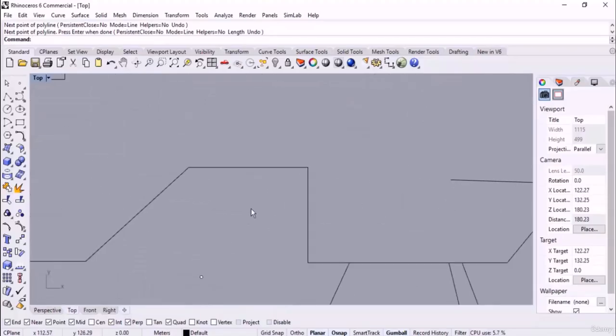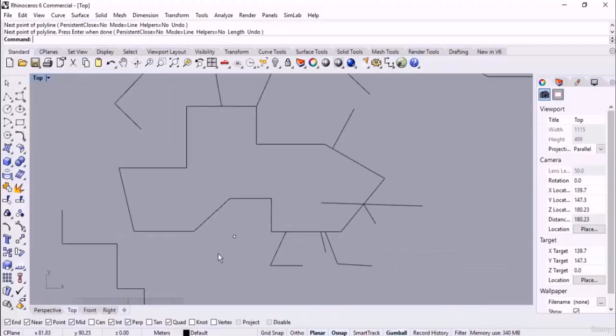But if you want one of these object snaps to be activated for a while, like midpoint, here if I right click on mid, as you can see, it deactivates the others, but midpoint. Right now the only active object snap is midpoint. We can reset it to the default mode by a right click. This is very practical. I want to repeat it.